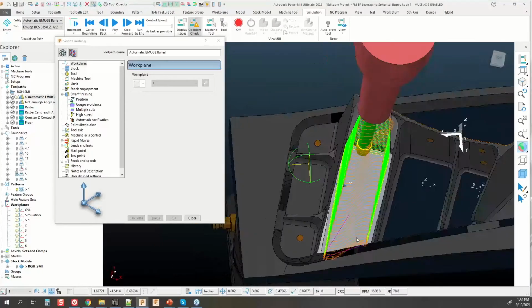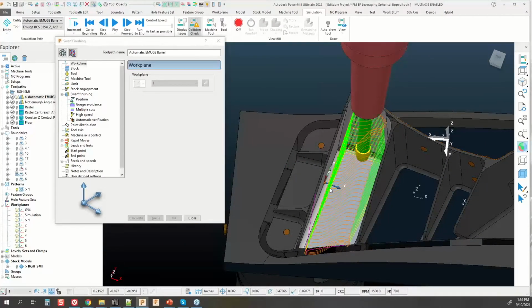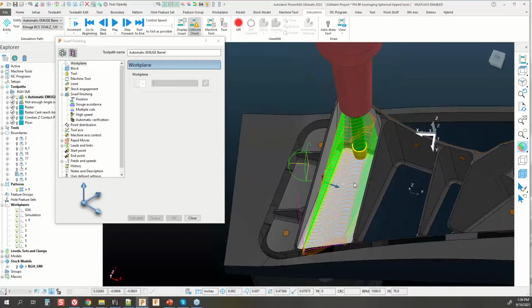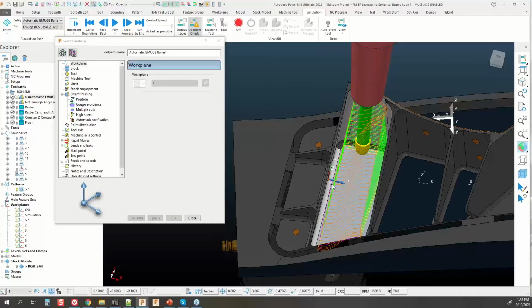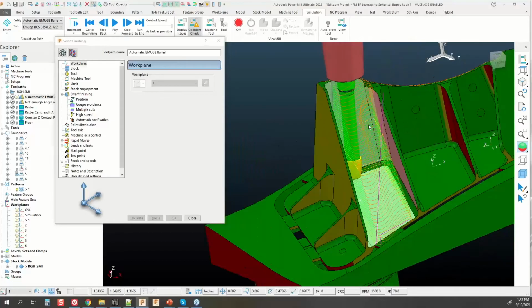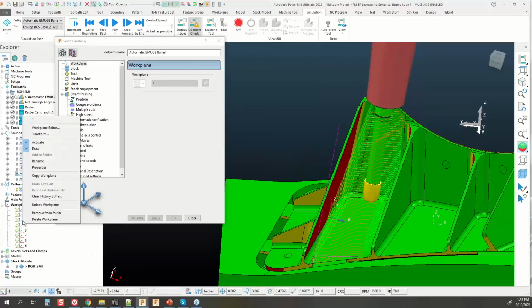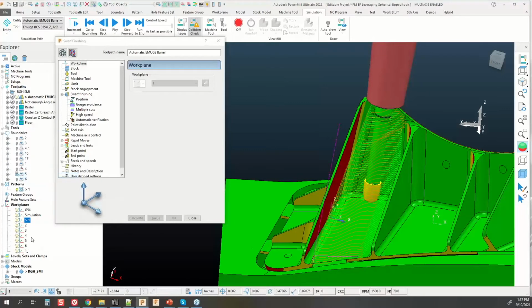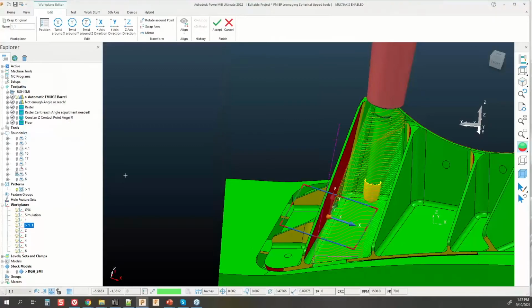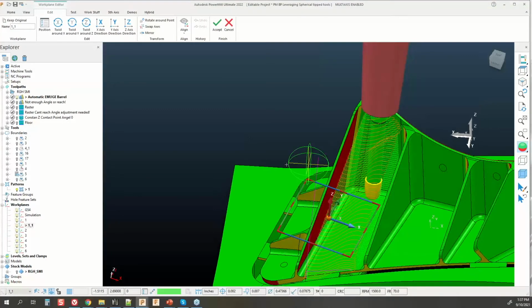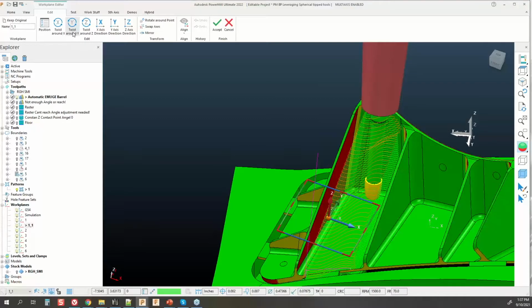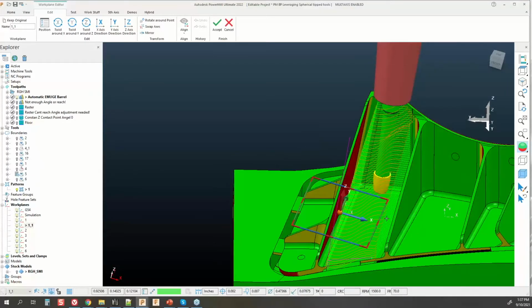All right, now that takes a little bit of playing with the initial work plane setup to figure out what type of clearance you may need or have. Now you can do a couple of things for this. You can utilize, of course, our undercut tool here that indicates where the undercut section is. You can also, and I'll copy the work plane for this, activate that work plane and go into the work plane editor. You can utilize any of the twist around options here to give you a little more clearance to try to find the average so that you can reach the majority of material here.